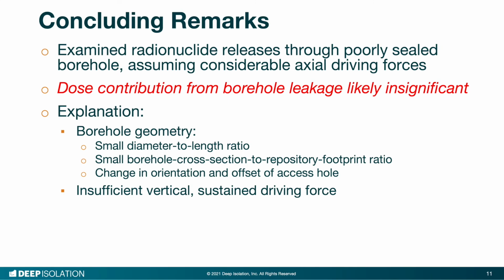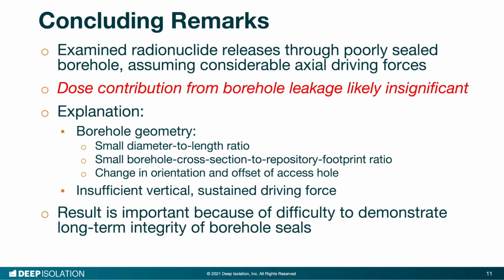Finally, strong vertical driving forces are difficult to emerge in the deep subsurface, and the source of water that would sustain them over a long time period is difficult to find in a suitable host rock of low permeability. The fact that we won't need to rely on the integrity of the borehole seals is a good result, because it is difficult to prove or demonstrate that borehole seals will last for the very long time of the repository performance period.